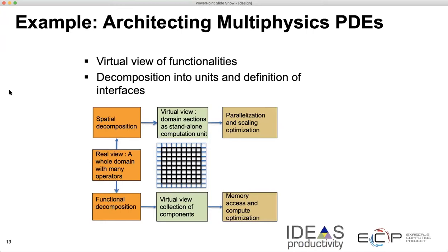As we all know, for explicit methods of solving, domain decomposition is basically your cells that you want to update surrounded by the halo of cells that are obtained either from an external boundary or from a neighbor cell. And when you do that, the solver cannot tell the difference between the full domain and the partial domain that you're giving it to solve.